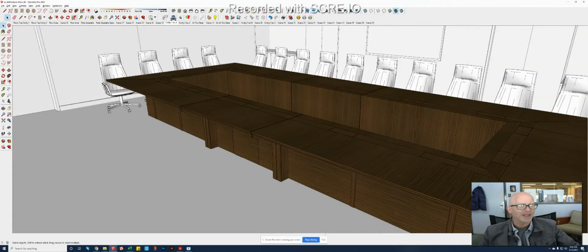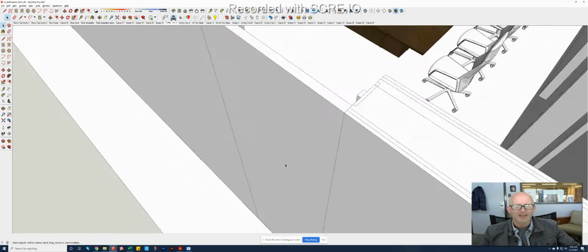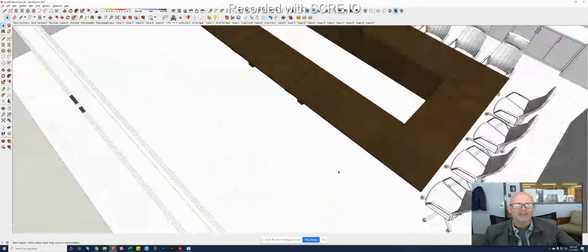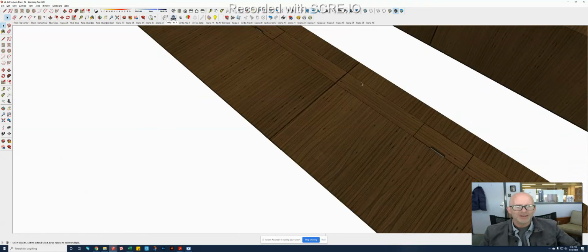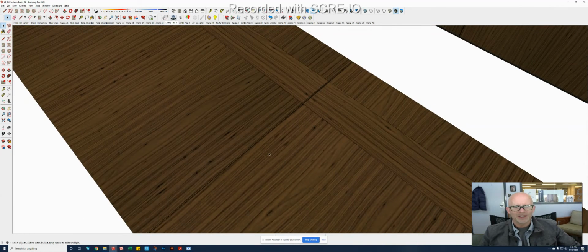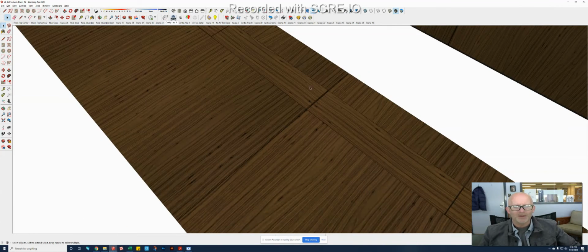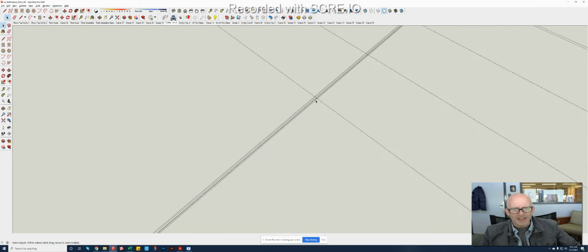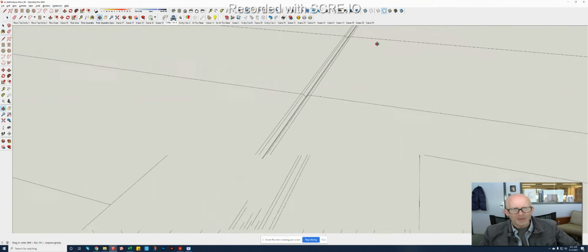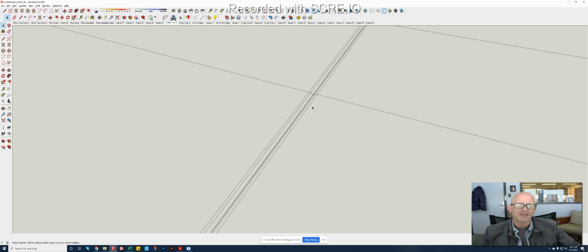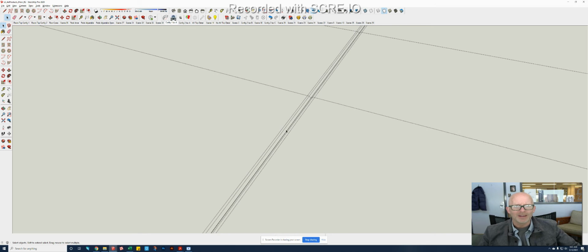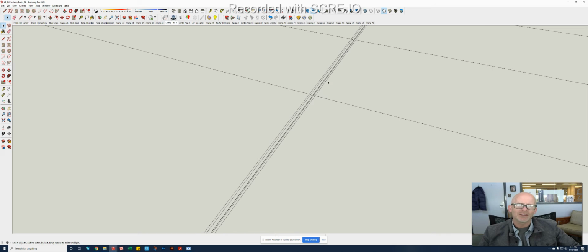Now, the way that this table connects to the U-shaped table. A couple things. The edge. Along the edges that meet, both on the fixed U section and on the modular sections, on each of those pieces, there will be solid walnut that's glued to the edge. That solid walnut will have a small micro bevel, a little 16th inch chamfer.